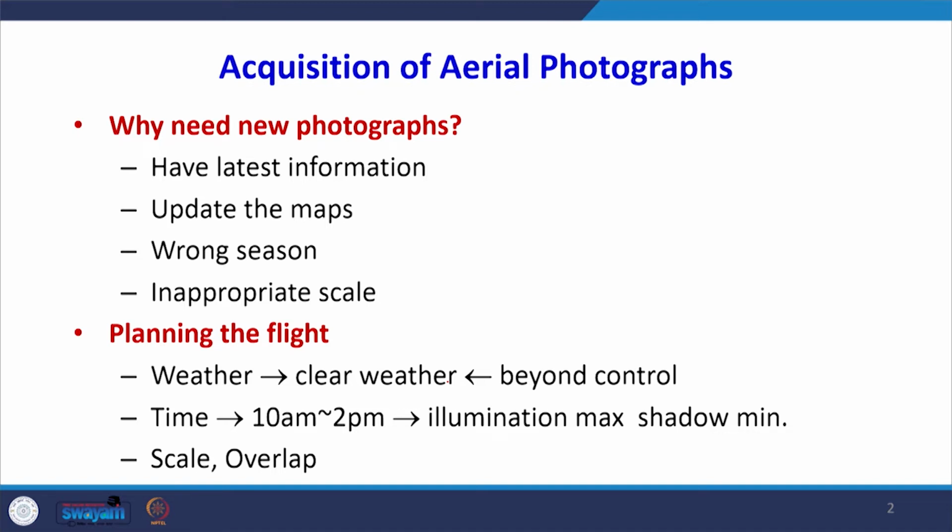Sometimes the season may not be correct for the measurements we are carrying out, or the scale of the photography may not suit. Scale is also very important to us whenever we are dealing with a small scale or large scale photograph, because the amount of information which you are going to extract will change. So, all these parameters are responsible. That is why we need a new photograph every time. One set of photographs may not be used for a much longer time, primarily because the information is changing very fast.